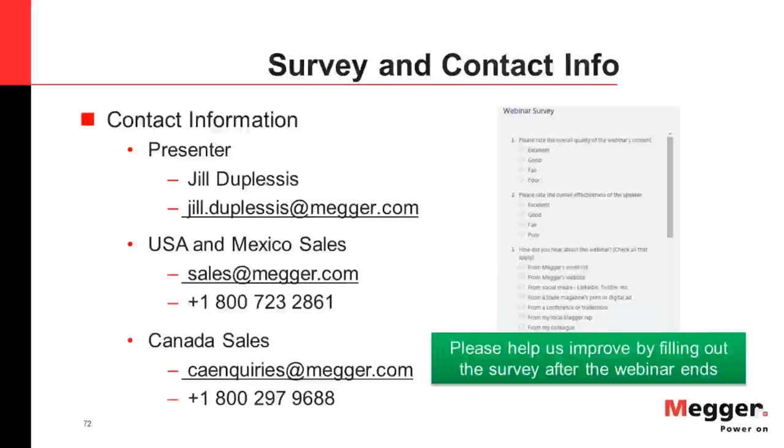Okay, thank you, Volney. And if I may, I'll continue and add to that as well. Since I was talking about transformers for so much time during this presentation, I will say that if you get a negative power factor for, for example, CH, CL, or CT winding-to-ground insulation components, that is simply not expected under any circumstances.